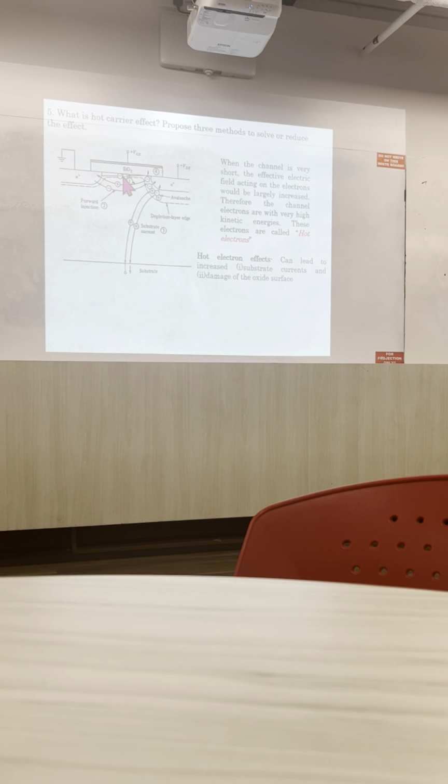That means essentially the electrons are like bullets. It comes, hits, creates electronic defects, not surface roughness, electronic defects. Okay, and those electronic defects can trap carriers. So in the picture in the lecture note, there shows how your transfer characteristic changes when you have damage, when you don't have damage, etc. Okay, when you have damage, you need to apply more voltage to fill up all the cracks and form the channel. Okay. So in the lecture, for sure, you have been introduced to one way of reducing the hot electron effect, which is that